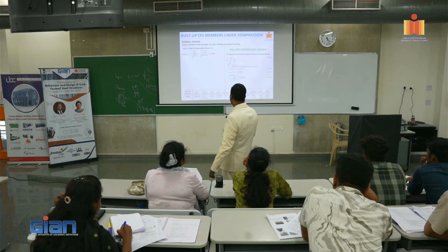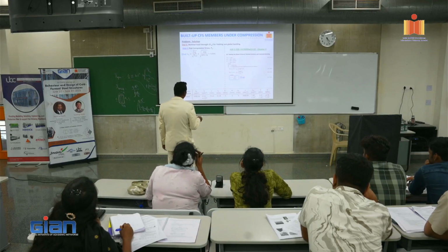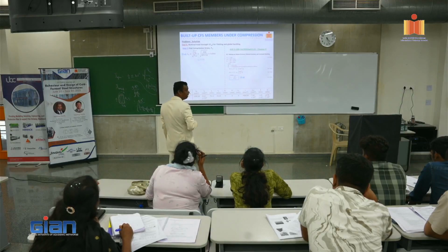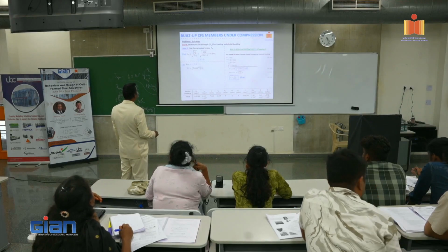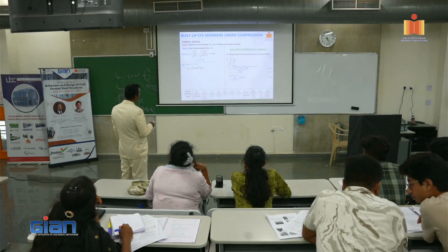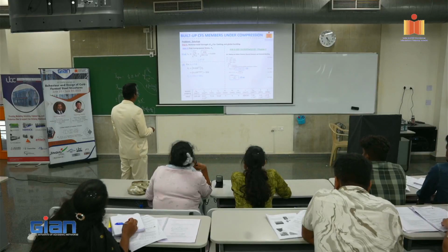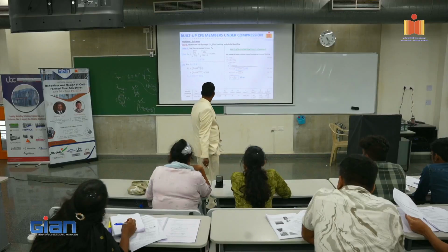Right? So I have to calculate this lambda sub c. It is 0.844. 0.844 is obviously less than 1.5. So I have to use the topmost equation. So I see that Fn equals 0.658 to the power lambda sub c squared, into Fy. I do that into 350, I get 259.77 as my Fn.